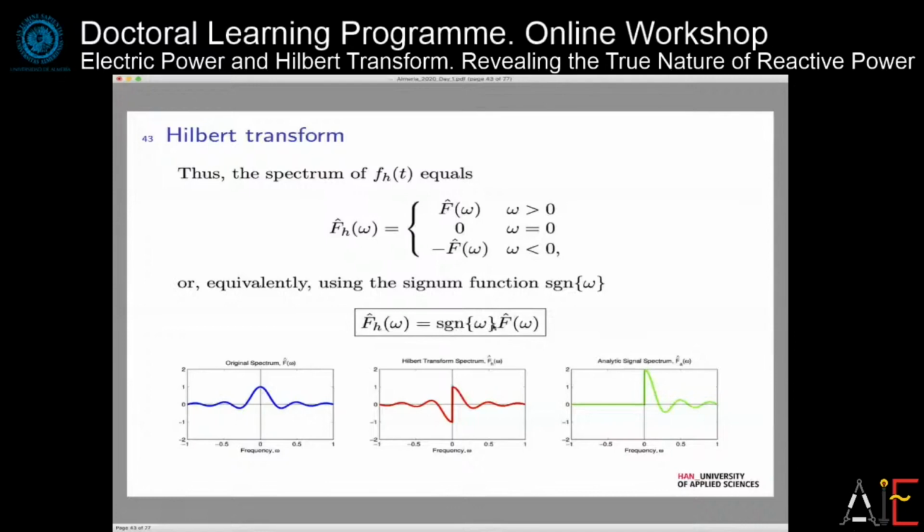It's given over here, another example. This is your original spectrum, which clearly satisfies this symmetry property on both sides of the spectrum, negative and positive; you just observe the same thing. So then you introduce this spectrum from the Hilbert transform of your signal, where you just have this part, then the negative of that one. You add them, and this is the spectrum of your analytic signal, which is twice as high because you want to keep the energy.